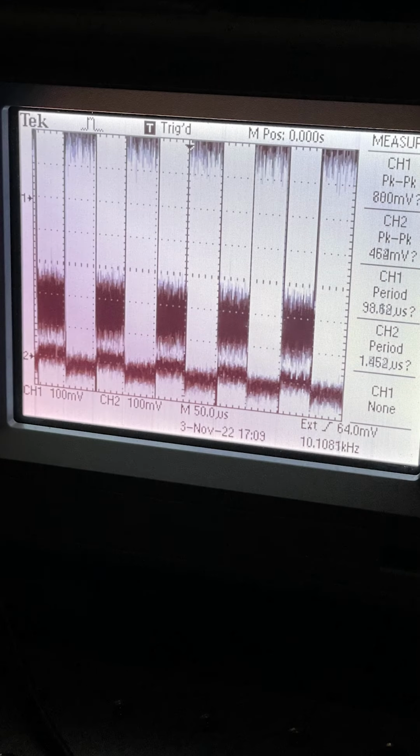For part A, we are observing different detectors and their properties. So for part 1 of part A, we set up an APD and PC for the same LED. We covered it with a black cloth and we set it to observe a signal to noise ratio of 1 for our photodiode, and we were still able to detect a clear signal with our APD.